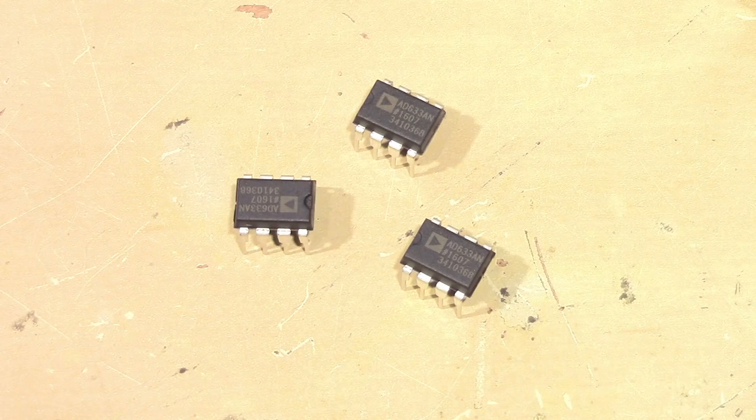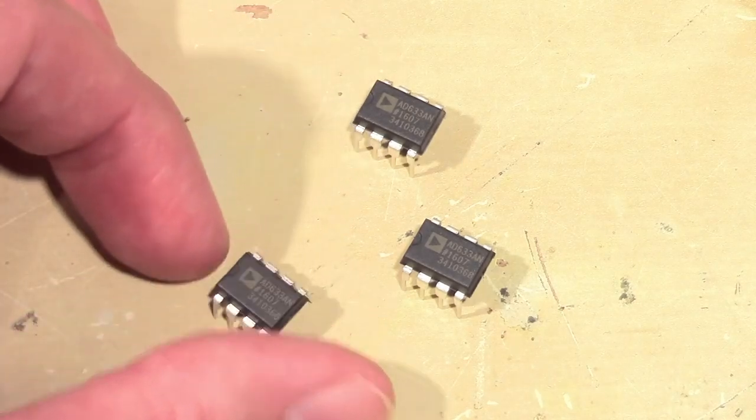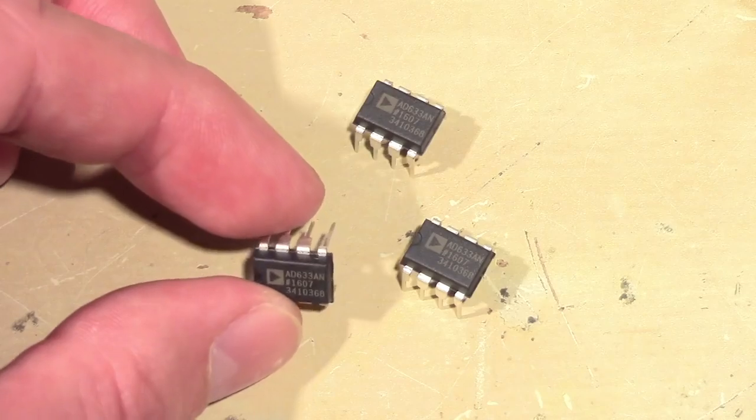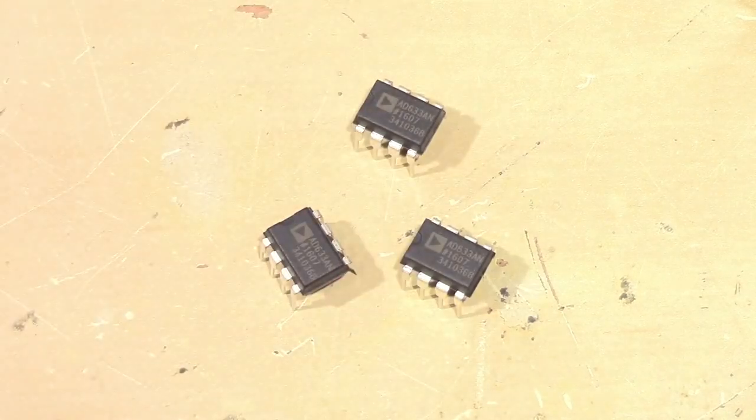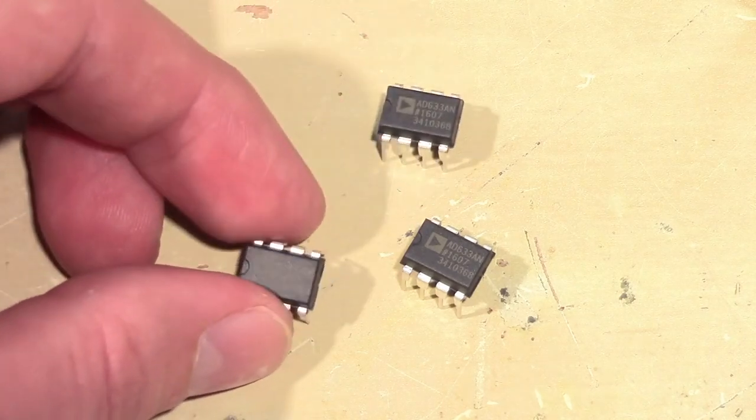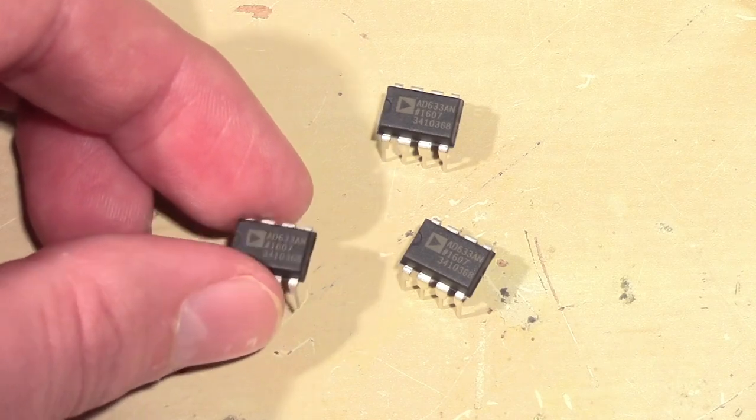Now, there are a variety of ways that you can achieve multiplication of two voltages, either using discrete circuitry or op-amps. All of those methods tend to be pretty finicky. You've got to have a lot of tweaks, and they also typically do not perform very well over temperature. So usually, if you're going to use one of these in your application, you're going to want to buy a pre-trimmed one. These are laser trimmed at the factory, and they work quite well. And Analog Devices makes a relatively inexpensive component called the AD633, which is an analog multiplier.